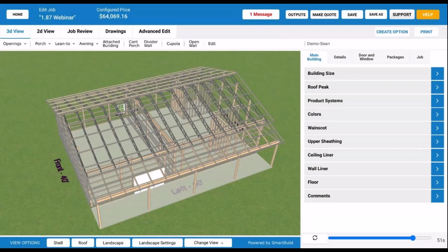With the TAS interface that we're talking about with the Simpson Truss program, very, very different. It actually is doing real-time complete engineering on that truss. And what you're looking at in the 3D picture then would be the truss as it actually will be built and has been engineered. So it'll show, for example, a 2x8 top cord if that's what's required. And it will actually show the real size connector plate that would be on that peak joint, for example. So anyway, that's the distinction there.